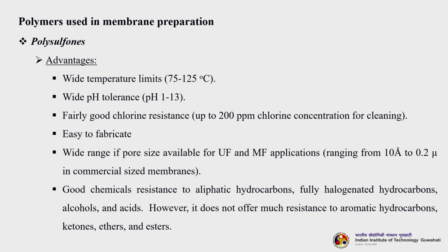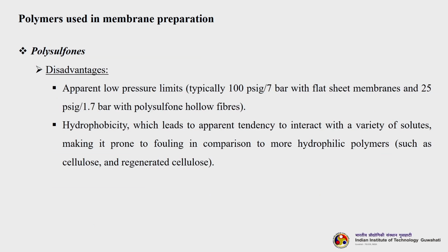So, it has good chemical resistance to aliphatic hydrocarbons, fully halogenated hydrocarbons, alcohols and acids. This means that polysulfones have extremely good chemical stability towards most of the chemicals and solvents. However, it does not offer much resistance to aromatic hydrocarbons, ketones, ethers and esters.